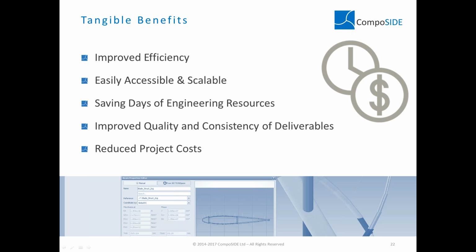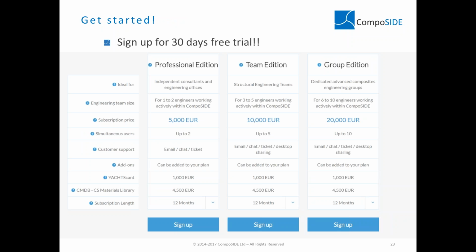Obviously, improved quality and consistency of the deliverable is a strong point, and the link with integrating the laminate table into the drawing with the weight is greatly appreciated by manufacturing engineers. So they've got a clear target to deliver that helps them in their quality control to have both the engineering and the manufacturing bill of materials.